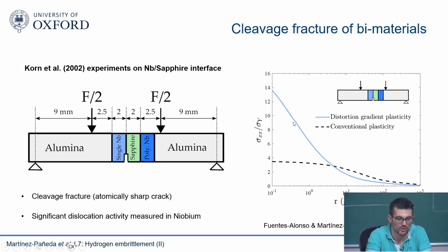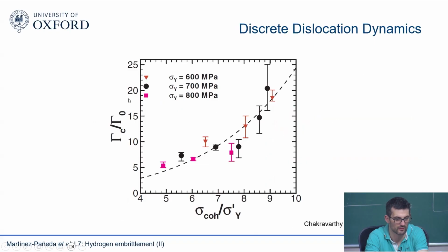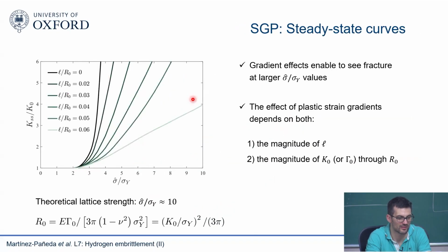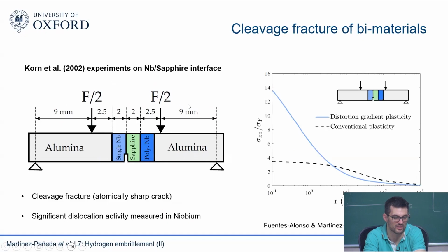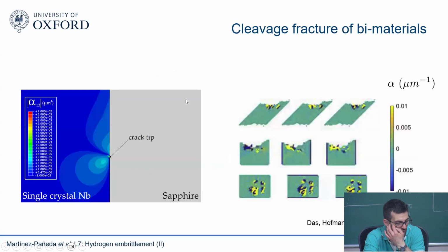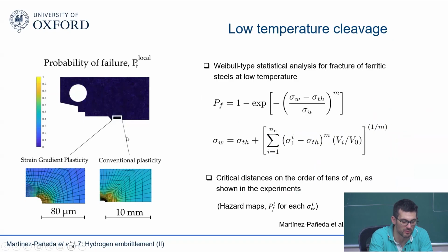It seems that basically when we put the right L and the right L0, the stresses are not here as they would be. In this case, they are more or less somewhere here. So this seems to explain what happens here. And in fact, then we plot dislocation densities and we compare with some synchrotron measurements. This is the Nye tensor, and we can see that the densities that we get on the Nye tensor seem to be on the same order of magnitude that they're seeing in the synchrotron. So it seems that it can explain this.